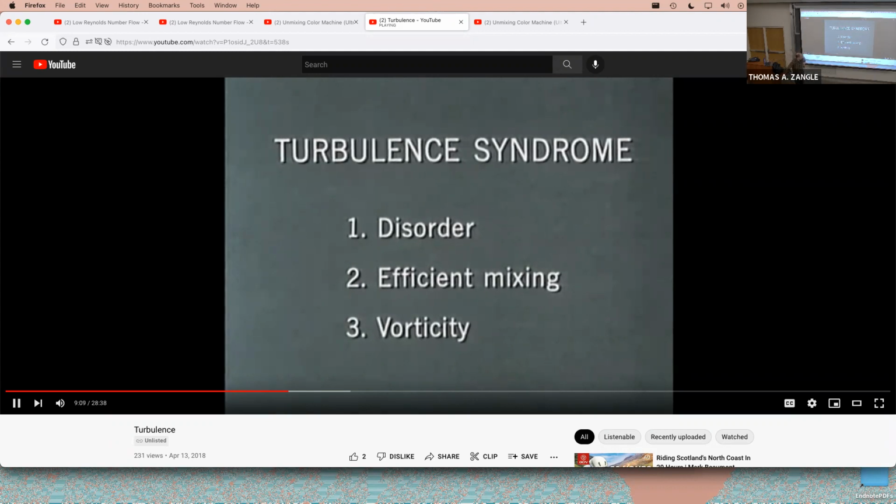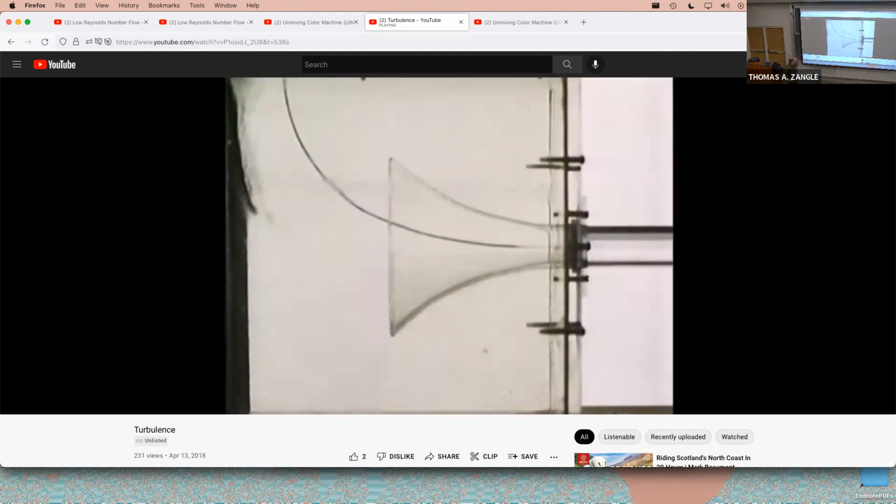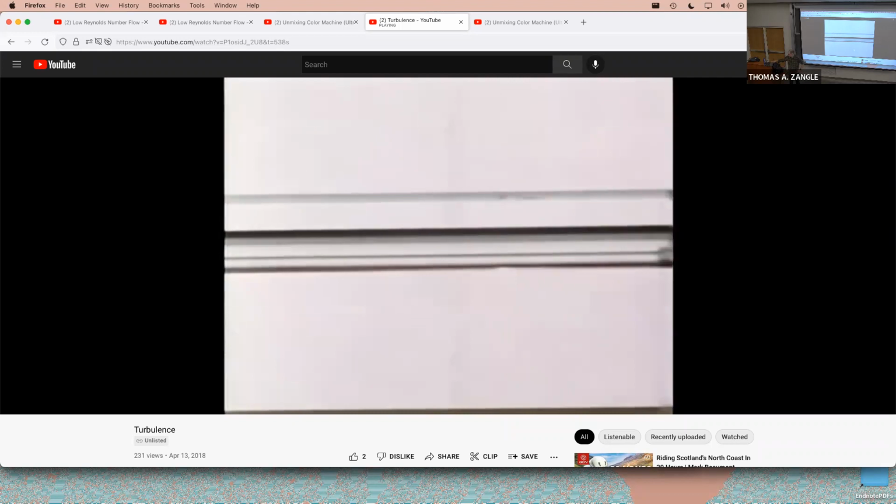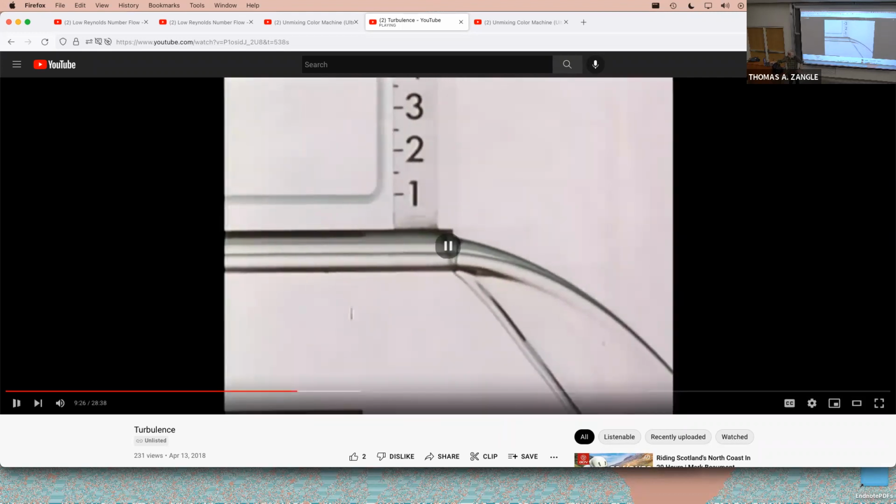Streamer of dye into the flow. Notice that the dye forms a thin film, maintains its identity with very little change right down the tube. The only mixing is molecular, and the concentration gradient is so small that this process is very slow. It's laminar flow in a tube. Reynolds number is maybe 100 or so.